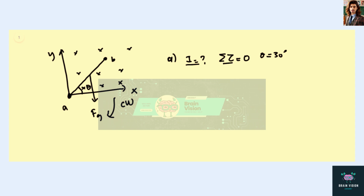Then, if we want the rotational equilibrium, we have to have a force that is forcing the bar to move counterclockwise so that they can balance each other out. So from this logic, we know F_B should be along a particular direction so that it would cause the bar to rotate counterclockwise because it needs to oppose what the gravitational force does.